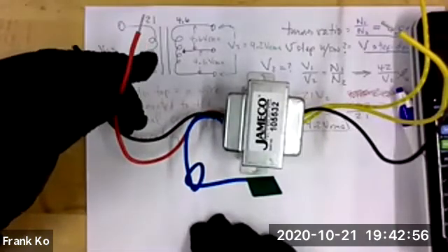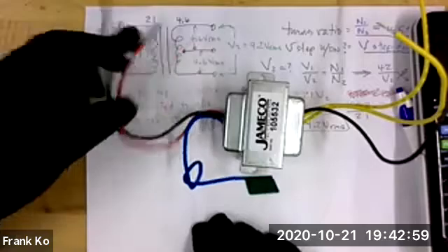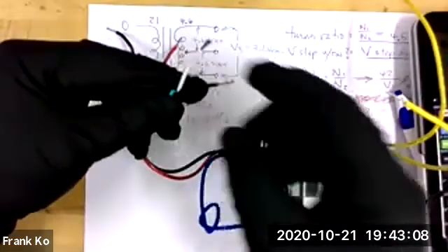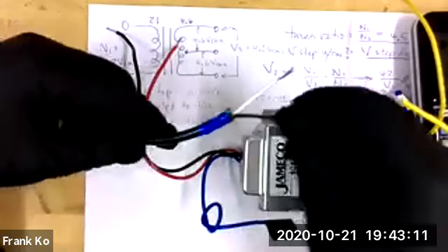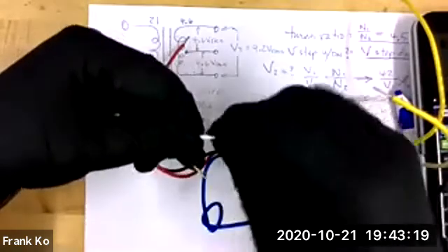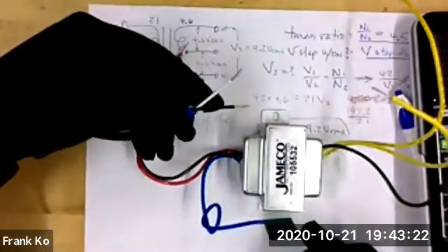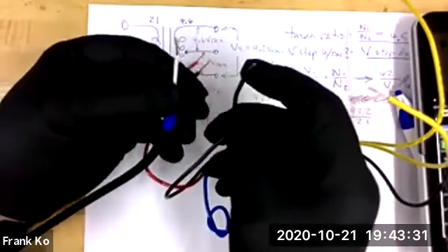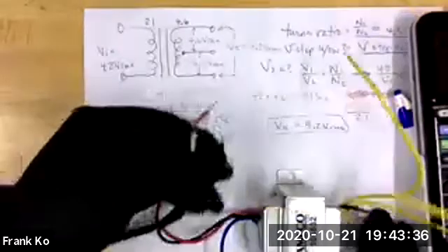So if you would please, we can do this. Take your power cord. You've already cut the power cord so that you have a black wire and a white wire from the power cord. Get your copper strands and twist them tight so that there's no fraying, no stray wires. You twist them nice and tight together. Do you have a black on the primary and a black on your power cord? Yes? Okay, so watch this on the camera, if you would.